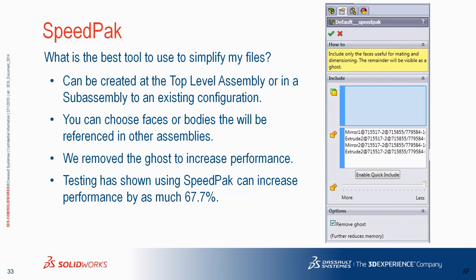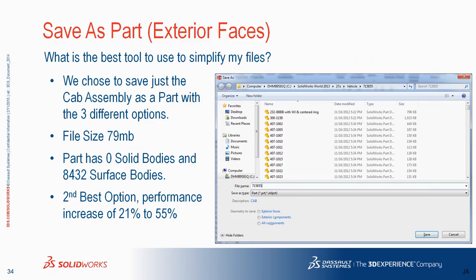And that's exactly one of the aspects where you would want to use something like SpeedPak, because it's a huge subassembly, and you've probably got a group working on that anyway, and all you need to do is have it there so when you're running a pipe or a cable harness from one side to the other, you don't run into it. You don't take up its space. So it's a perfect example of where this would be used effectively.